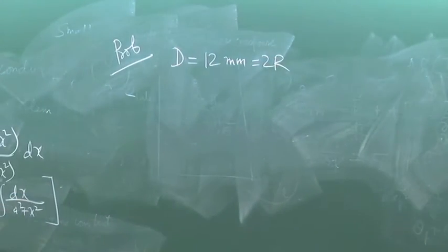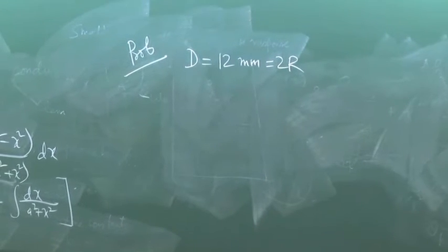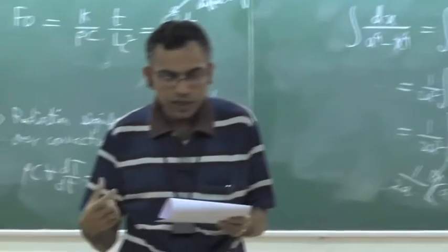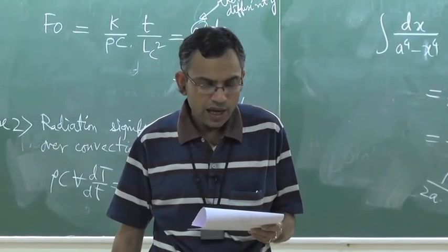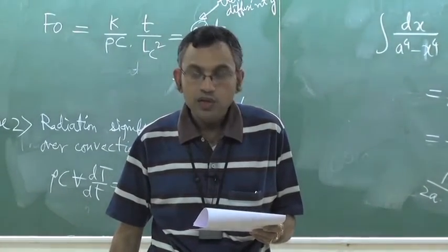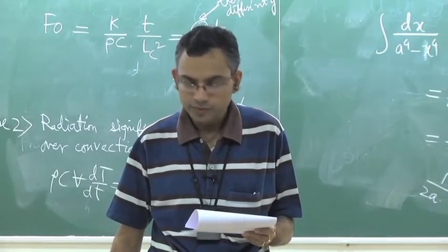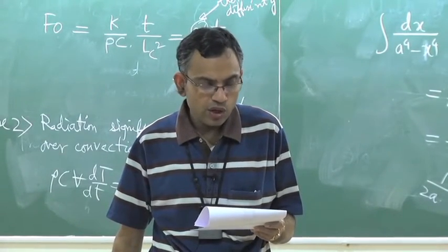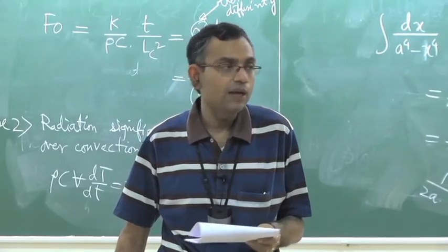Are annealed. Annealing is a heat treatment process. They are annealed by heating to 1150 Kelvin and then slowly cooling to 400 Kelvin.